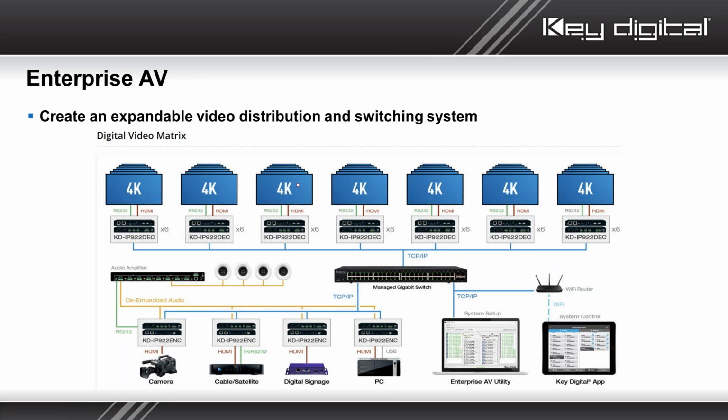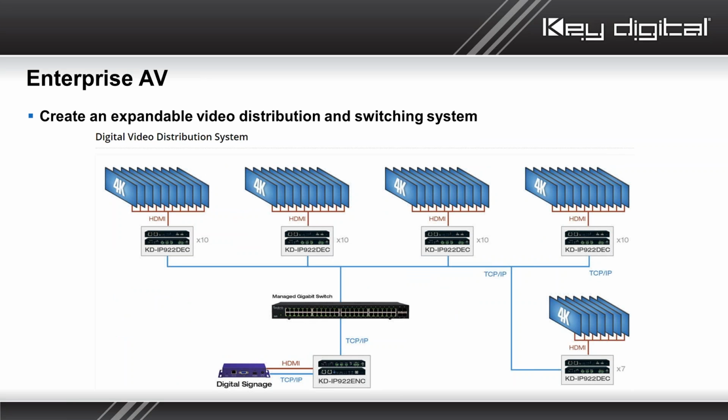And we're able to do that by using a traditional managed gigabit network switch as the centerpiece, as the video distribution point. We're also able to get very significant distances out of systems like this. You could go 100 meters into the network switch from your video sources and another 100 meters out, and that's using traditional cable, copper I should say, Cat5e and Cat6. So some very appealing points to HD over IP that has brought a lot of attention to the technology.